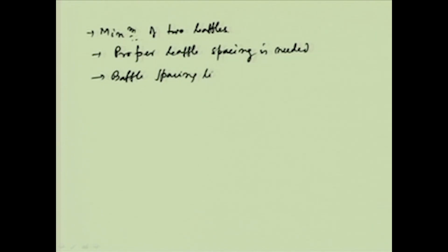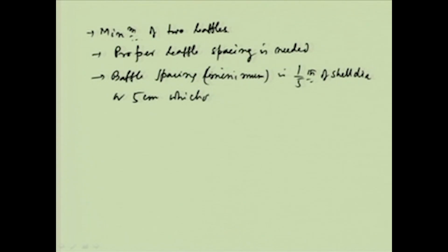lies, the minimum baffle spacing, I should say minimum, is 1/5 of shell diameter or 5 centimeter, whichever is larger. So, that is the minimum baffle spacing that should be used.